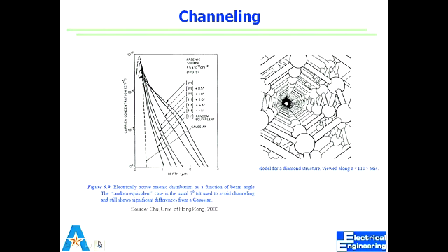Now think about it. If I have an SOI wafer and my SOI is 200 nanometer, do I really care what my orientation should be? It depends on how deep I want to do it. If I want to dope, it's micron. So up to this part, I don't care. This is less than 200 nanometers. It's clearly visible that it doesn't matter for me. Right? Make sense? So if I have SOI and my silicon is 200 nanometer, the silicon that I really want to dope is just 200 nanometers. Do I really care? No.